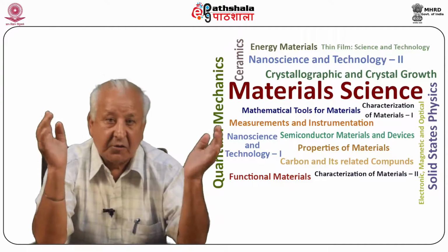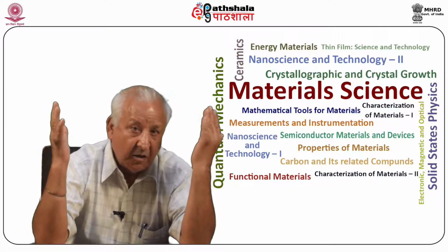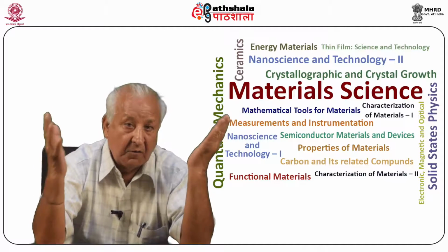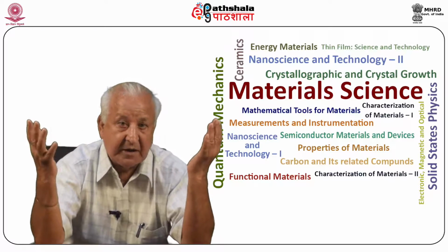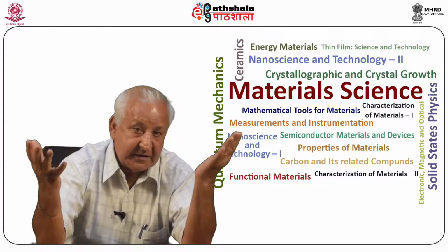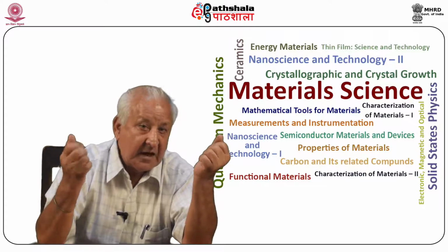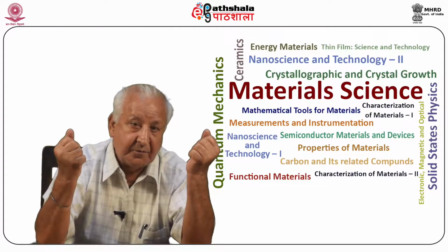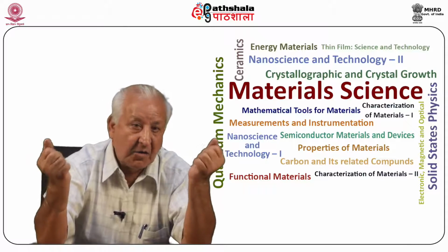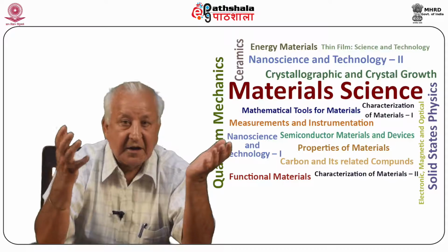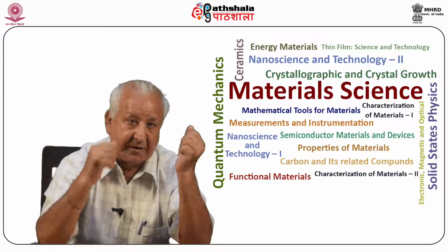This method requires a large power supply of the order of 35 kilowatt at 10 to 100 volts. The technique is utilized for obtaining low-cost crystals of materials with high melting points, which are difficult to produce by other techniques. Like Verneuil growth, here also melt is created in contact with its own solid.